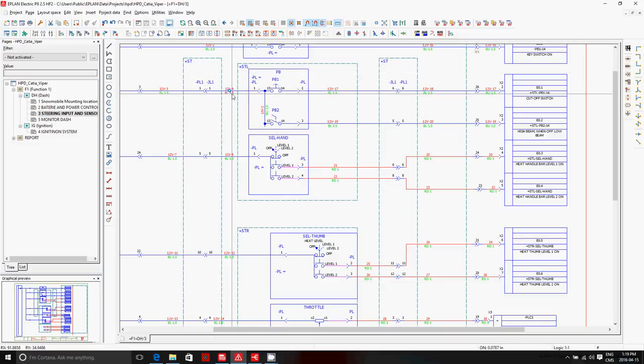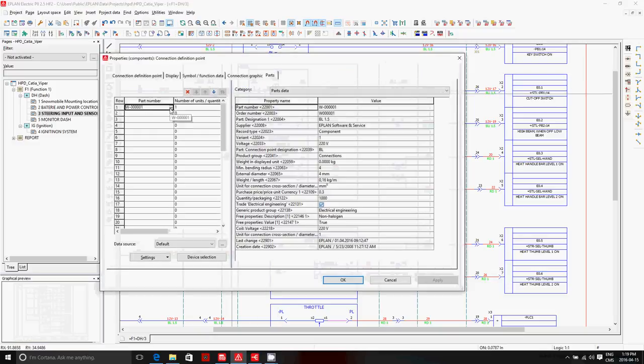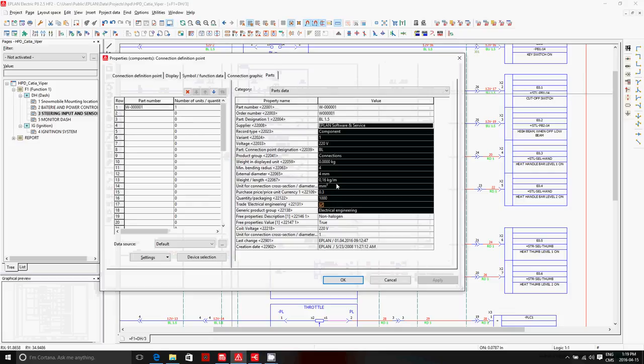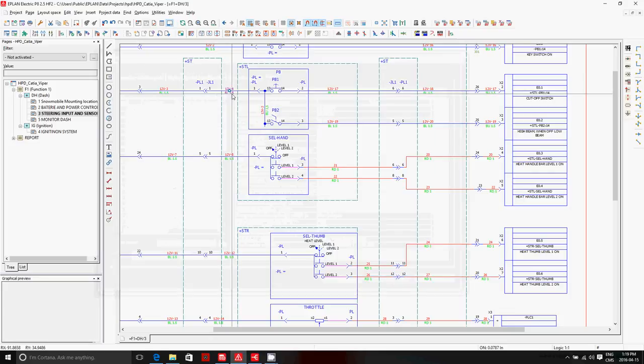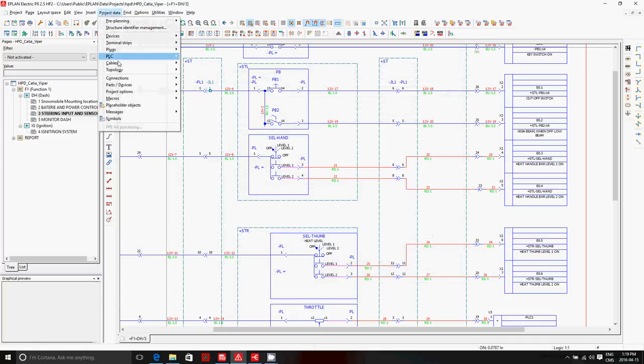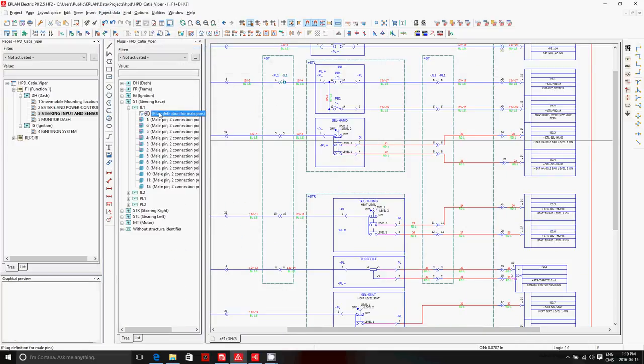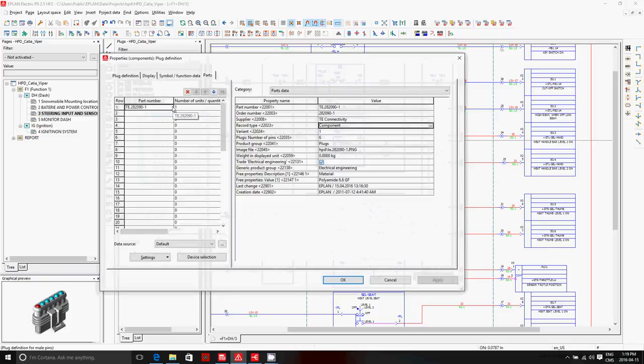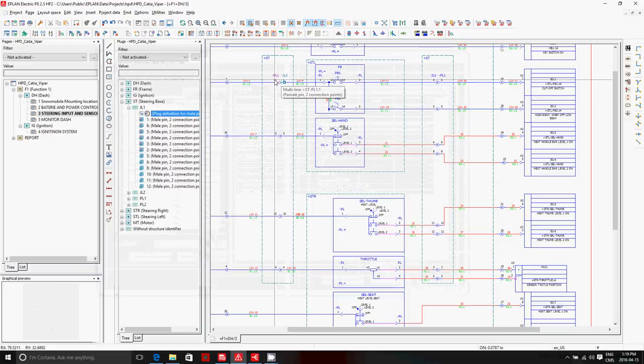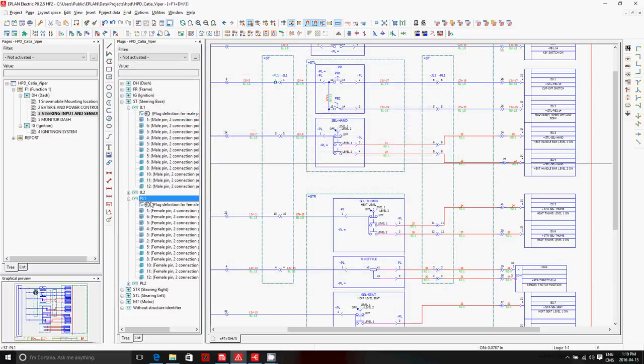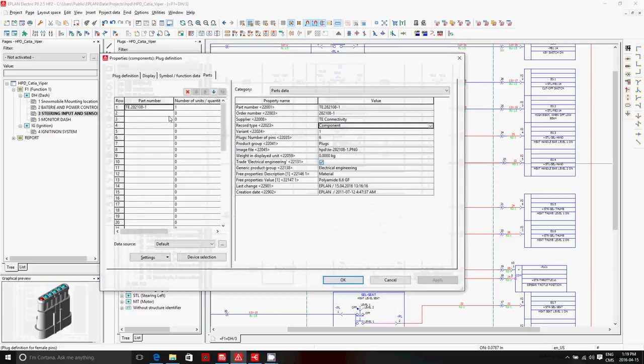So here we have a wire. Each wire, of course, has a part number, so we know what the size of the wire is, what the gauge of the wire is, the color of the wire, and then we have connectors. These connectors, like every other connector, has, of course, a part number. Here we can see we have actually a plug, and you have the counterpart, which is basically on the other side here, the PL1, which is the female portion of that connector.